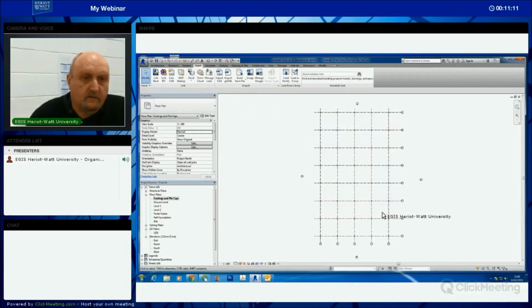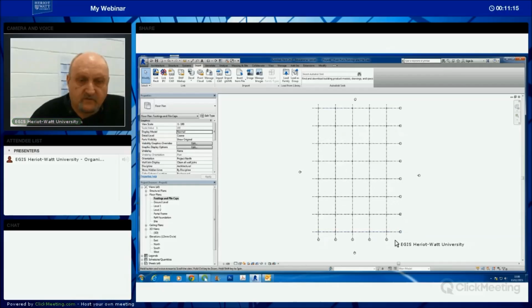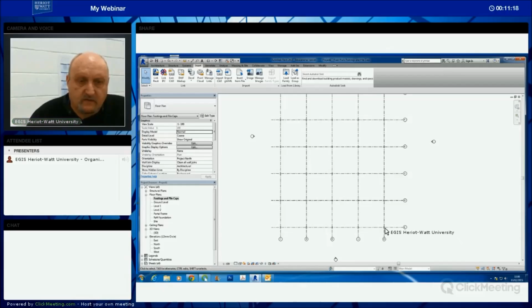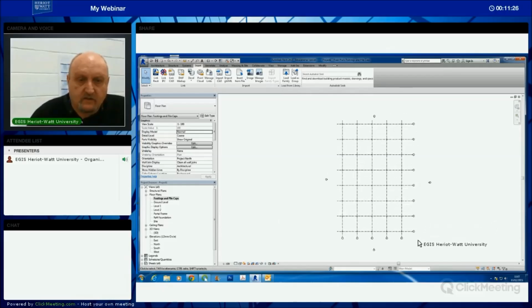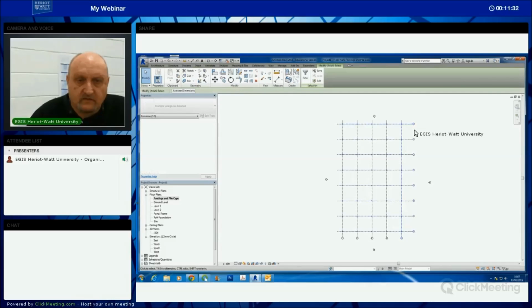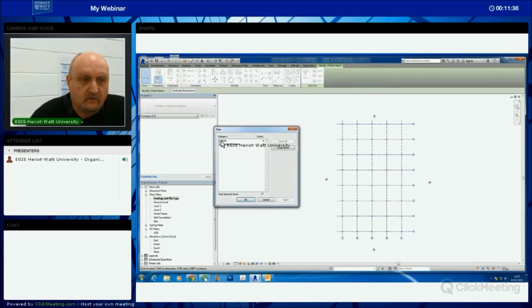And I'll do the perimeter columns first. And just before I load these columns, the columns down grid line 5 and down grid line 1 have to be flipped. Their orientation has to be changed. So I'm going to over select. I just simply mouse over, select them all, and clearly I've got all kinds of things going on here, grid lines, and so I filter them out. I don't want the grid lines, only those columns do I want selected.